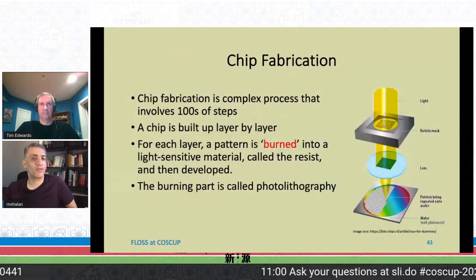In ASIC, software testing is equivalent to several activities done before and after chip fabrication to ensure that the chip will be or is functional. This includes several verification steps during the development process, and this is typically done either through simulation or formal methods. And after fabrication, we test the chips against manufacturing defects.